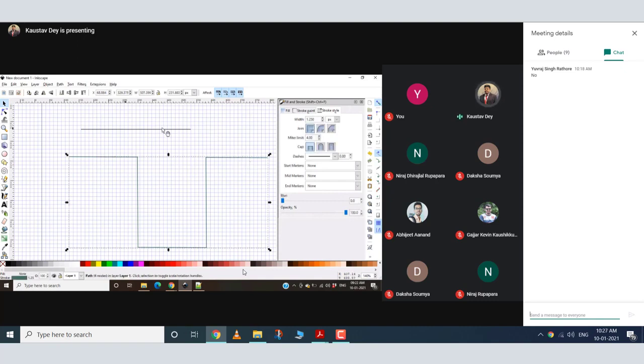And you can do this very easily for all the lines. So I select this line, the features of this accordingly come up. See, in px unit it's 1. So I also want to make it say 1.25. Now both these lines are of the same thickness. This was, yes, 1.25 and 1.25. Now what if I want to put a marker, say an arrow, at the end of the line? So this marker usually comes in start marker, mid marker, end marker.